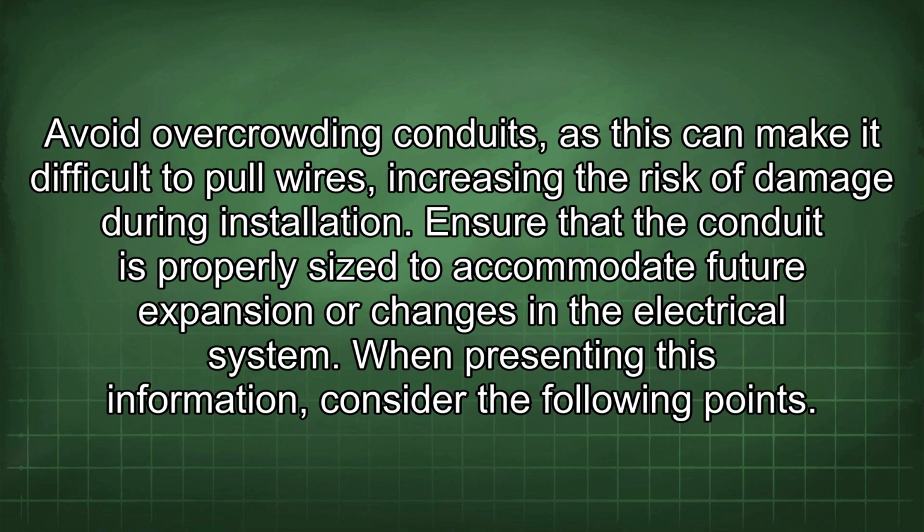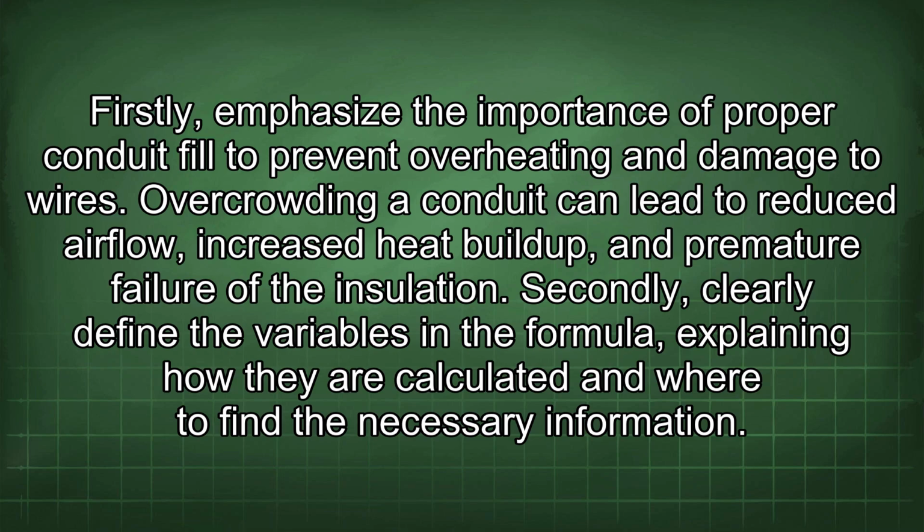When presenting this information, consider the following points. Firstly, emphasize the importance of proper conduit fill to prevent overheating and damage to wires. Overcrowding a conduit can lead to reduced airflow, increased heat buildup, and premature failure of the insulation. Secondly, clearly define the variables in the formula, explaining how they are calculated and where to find the necessary information.